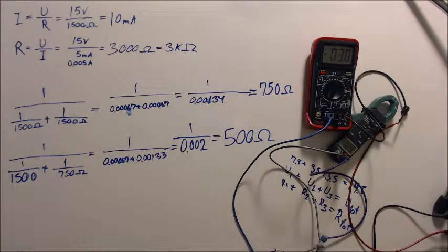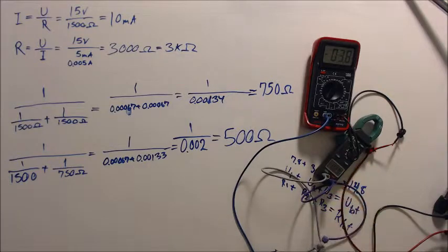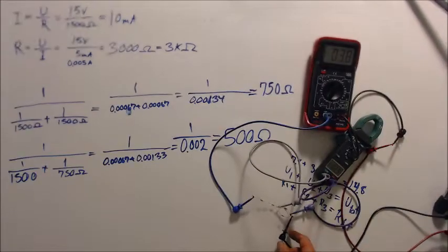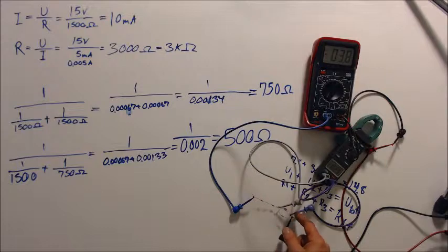So as you see, now it's not an even halving of the resistance by putting in another resistor, and now we can analyze how much current goes on each resistor by using Ohm's law again. And we know there's 3 volts, and the 3 volts are present on both sides in this parallel connection, on either one of the resistors. That's going to remain the same no matter what side you're measuring on. So we know it's 3 volts.